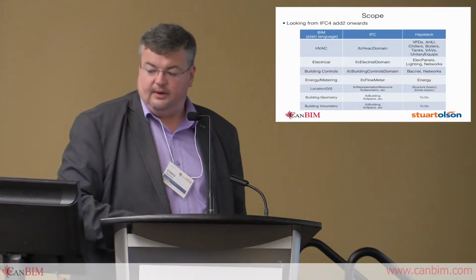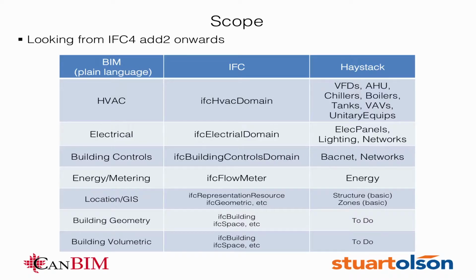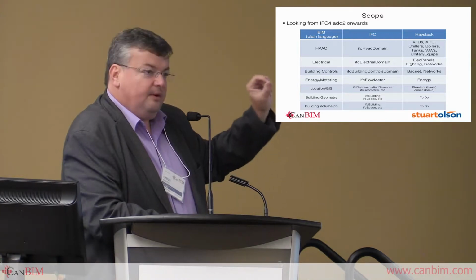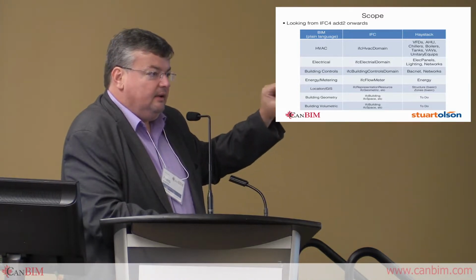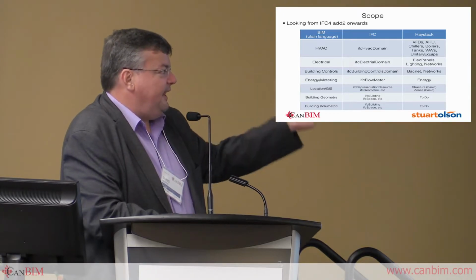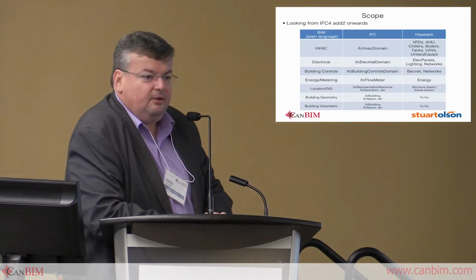So what we've done is define a rough draft of the areas that we'd be looking at dealing with. So we have HVAC, and the IFC HVAC domain. I decided to at least start the conversation with the domain-specific classes of the IFC, because we already have, from a Haystack perspective, nomenclature for VFDs, AHU boilers, tanks, VAVs, unitary type equipment.